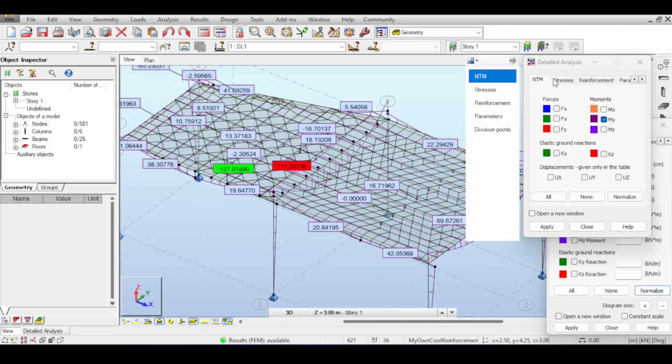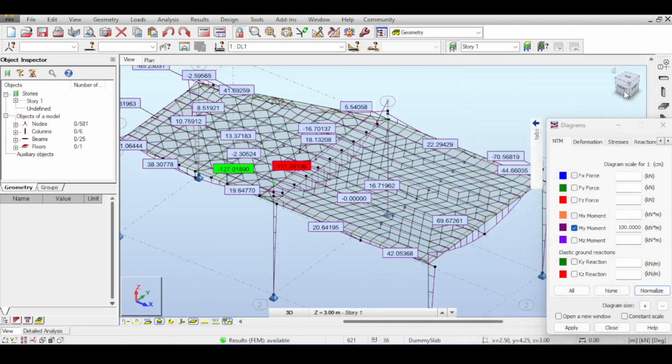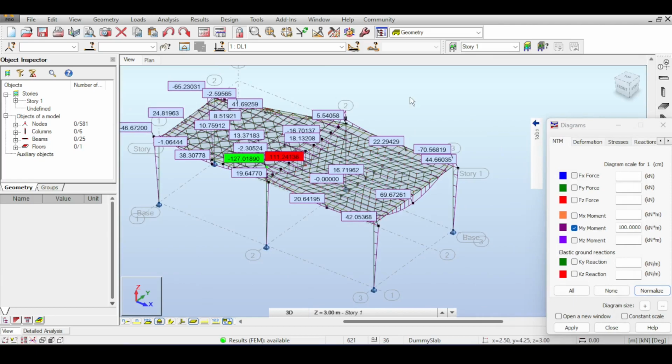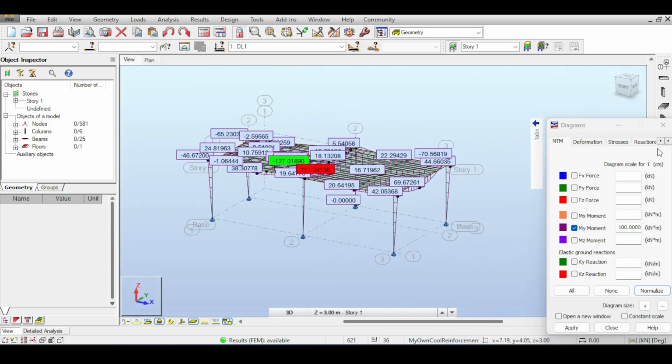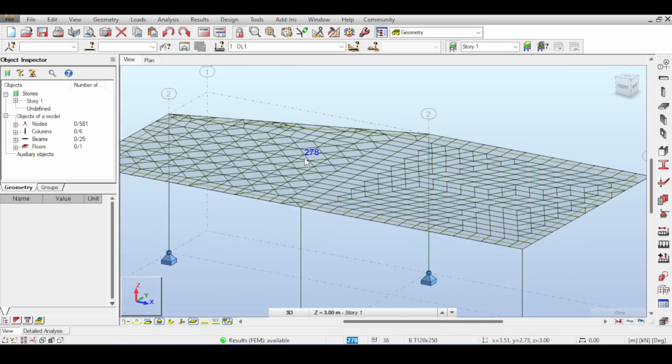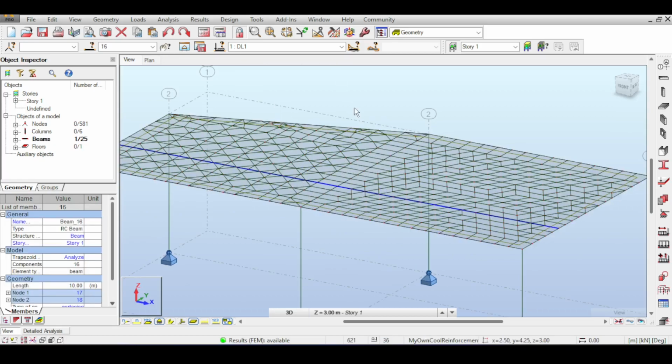It's kind of cool. And please notice that analyzing a ribbed slab in software is much, much more accurate than any approximate methods you were using in the university to approximate the load on the ribbed slab. Because in a finite element software, you have much more accurate interactions: the torsional moment of one element is going to affect the bending moment of the second element, and so on. Also, the torsional stiffness of the entire beam will affect the moment of the ribbed slab.